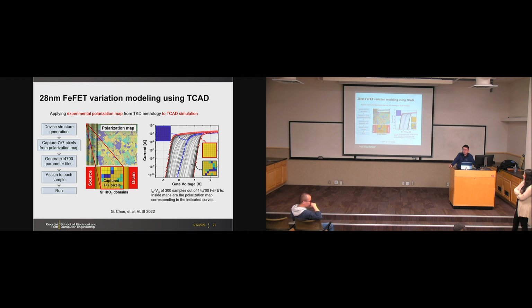Of course, when you run the TCAD simulation, you can verify the potential by solving the Poisson equation in the electrostatics. We have done the TCAD simulation to verify that. So you used the short channel effect, right? Yes, you have to have a short channel and the confined geometry. The channel thickness is only 10 nanometer or so.